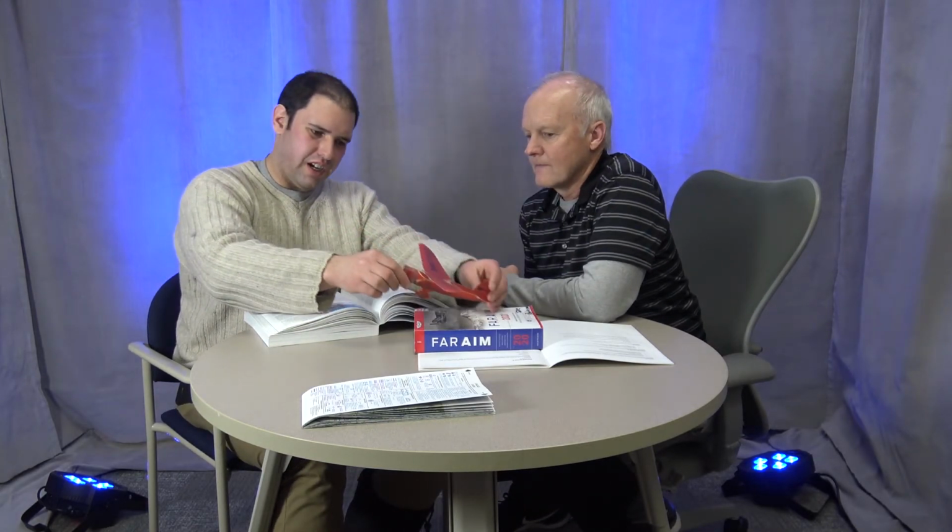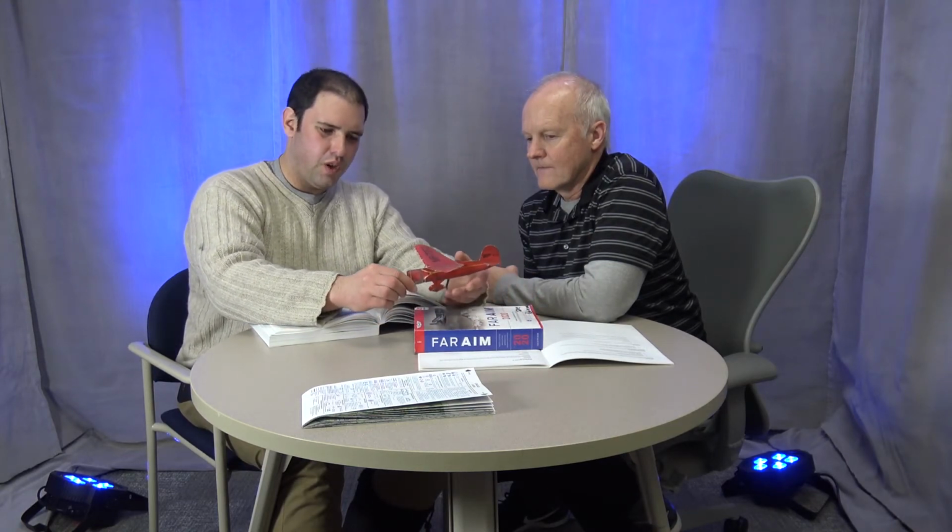So you get some interesting effects when you pitch the airplane. Because of gyroscopic precession, that force manifests 90 degrees in advance in the rotation. So, for example, if this model is a tail dragger, so if it's sitting on the ground and you raise the tail, as we do on takeoff, well, that propeller is a spinning gyroscope. It wants to resist, it wants to stay in the same orientation, it wants to resist that pitching.